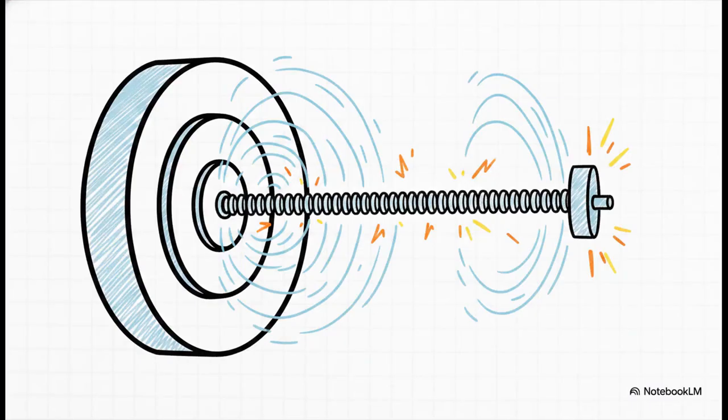So what actually happens the moment you close the circuit on a load? Well, a steady-state current starts flowing in the stator coils, and this stator current creates its own flux that actively opposes the main field flux coming from the rotor. We call this the armature reaction. The magnetic action taking place is literally a tangential pulling between the stator and the rotor. It is highly analogous to stretching a physical spring. The greater your electrical power demand, the harder that magnetic pull becomes, and the further you stretch that invisible magnetic spring across the air gap.